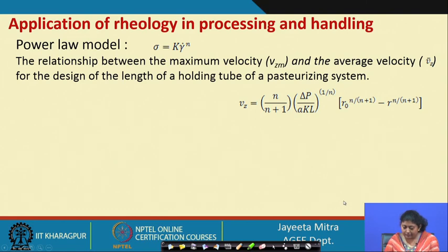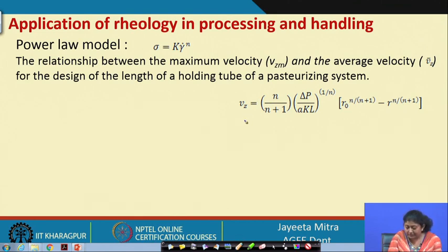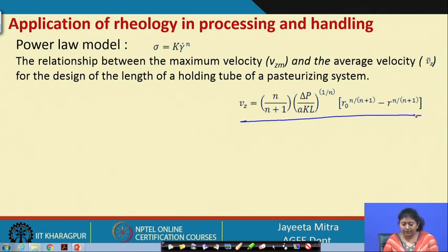Okay. So, for non-Newtonian fluid, z directional velocity can be simplified by this equation. Now, how have we got that? In the initial equation of Vz, we need to put the value of Vz in terms of this equation, which relates with the flow behavior index.